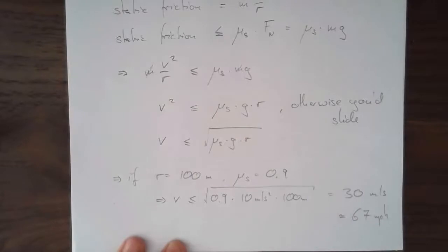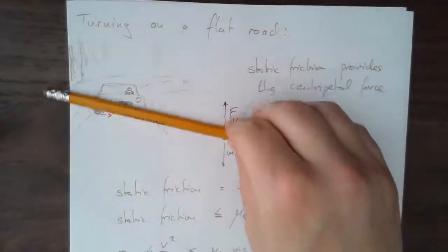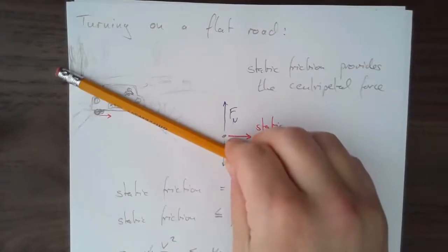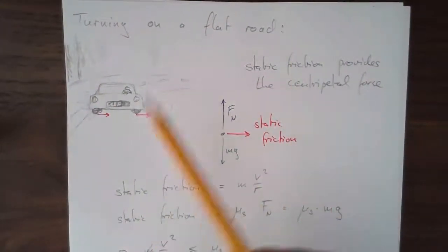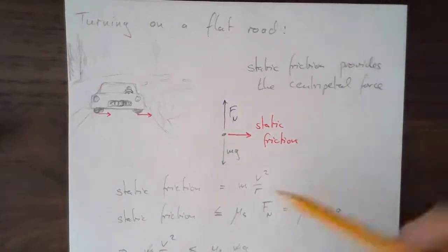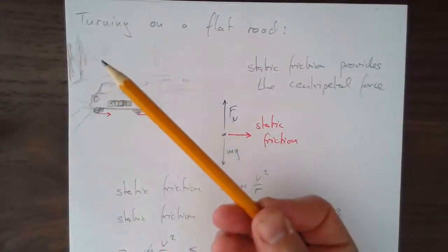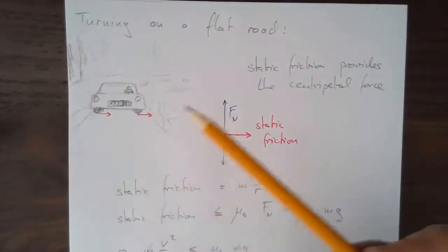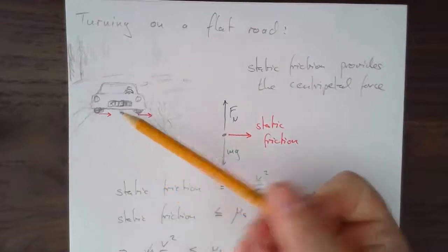Okay. Now suppose you want to go faster around a turn, right? Well, friction clearly is not enough. So that's where banking comes in. So banking means we take this road and we tilt it like this. Now, there are extreme cases of banking where it isn't about a road, but if you watch indoor cycle races where they go round and round, say some kind of Olympic discipline, their track is really steeply elevated because they go around so fast, it's almost like pushing against a vertical wall. Not quite, but it's kind of how it feels.